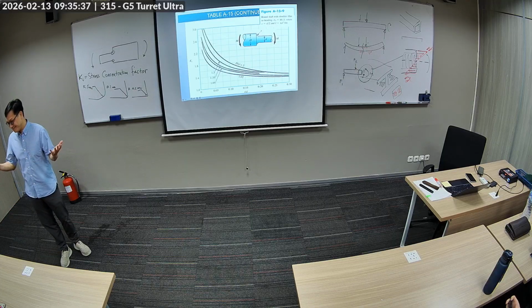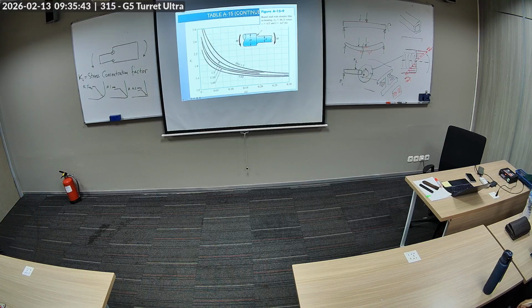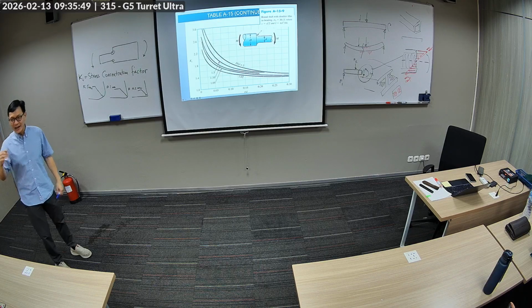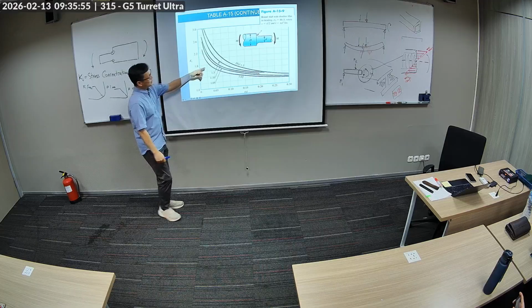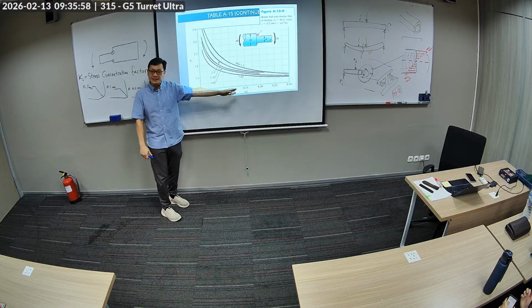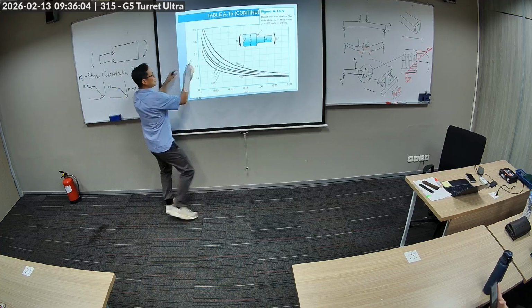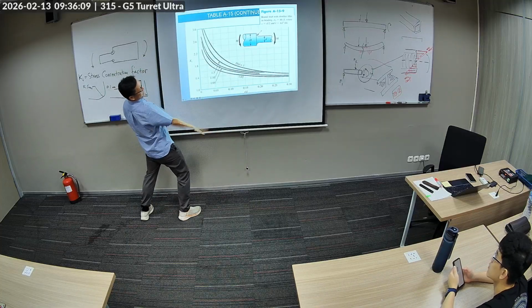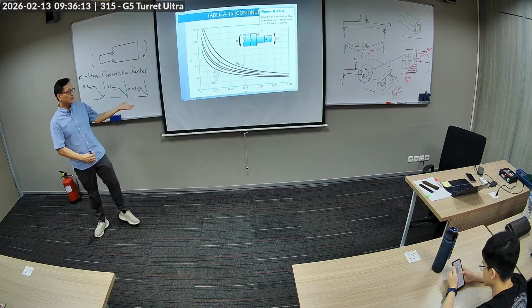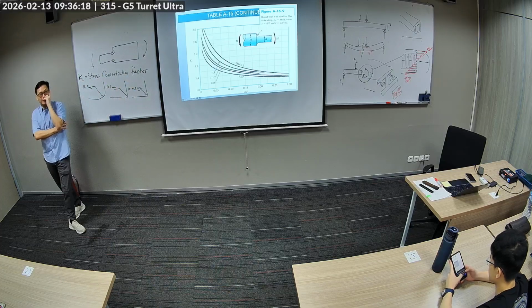We engineers, we approximate. You know, a good engineer, I think, can hold this in their hand and say, that's 100 grams. A great engineer has a good intuition to estimate something, technically, obviously. So, these lines, how are they generated? Lots of experiments. The dots kind of scatter, and then you just say, let's make an approximation. And so this chart is the guidance to determine stress concentration factor.